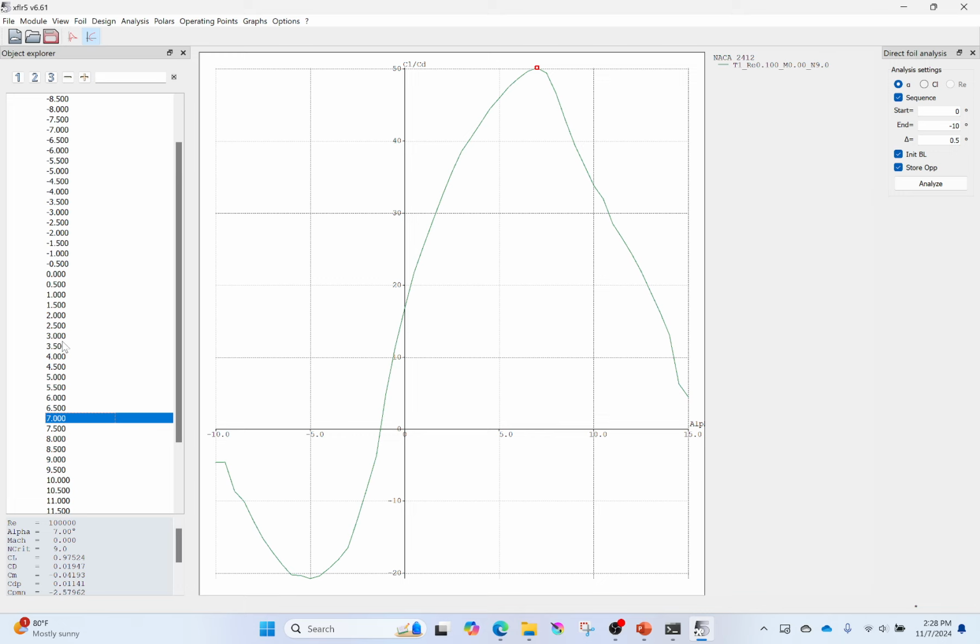And when you maximize this, what you find is the point where you have the highest glide ratio is actually the point where you have the minimal total drag force, not the minimal coefficient of drag, but minimal drag force. In the best situation, I want to be the most efficient for my fuel, then this is the best place to do it because this will require the least amount of thrust. And remember, thrust means I'm running my engine. If I'm running my engine, I am burning fuel. So least thrust means least fuel use.